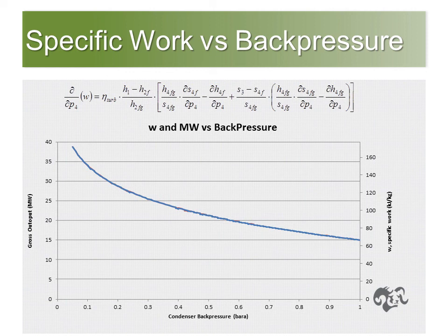But note that I haven't included the exhaust pressure loss curve in this equation, and so that would have to be taken into account, especially if you're able to operate at very low condenser back pressures.